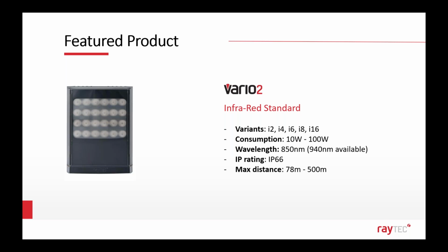Now, it should be pointed out that these distances are based on what we would perceive as security camera, CCTV type applications with something in the realm of a 1/50 shutter speed. Casting our mind back to the Zurich application, the cars are going to be slowly moving in, so it's unlikely that the shutter speed needs to be much higher than that. In applications where vehicles are faster moving, you would need a faster shutter speed, and then we would have to calculate those max distances differently, but we can touch on that a bit later.